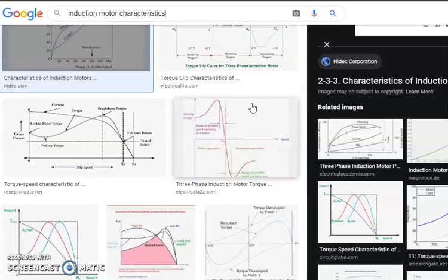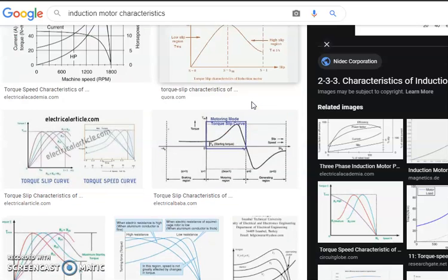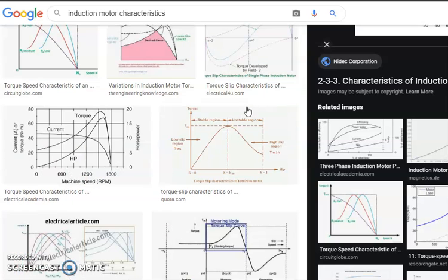So here you can pick up any kind of reference in terms of what response versus what response you need to obtain from your experiment and present. Let's say you have torque versus slip. For an induction motor, once your slip increases from 0 to some rated range, your torque increases, so the strength of your torque is increased. Once the slip goes over the rated value, it tends to drop. You can present this kind of result trend inside your report later on.